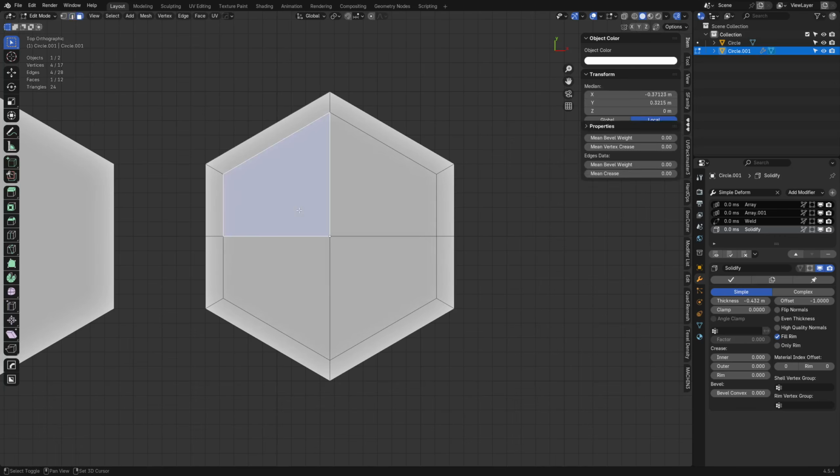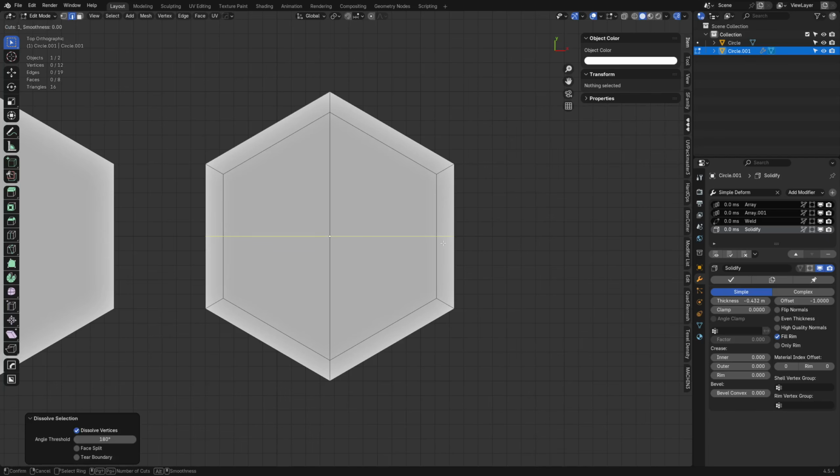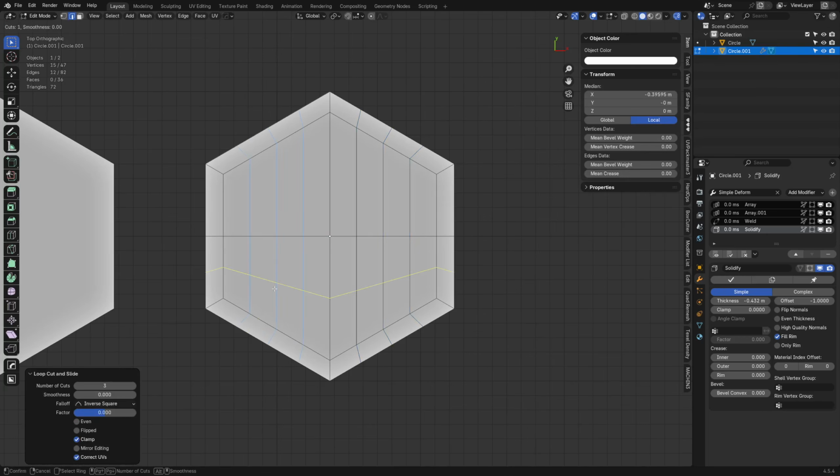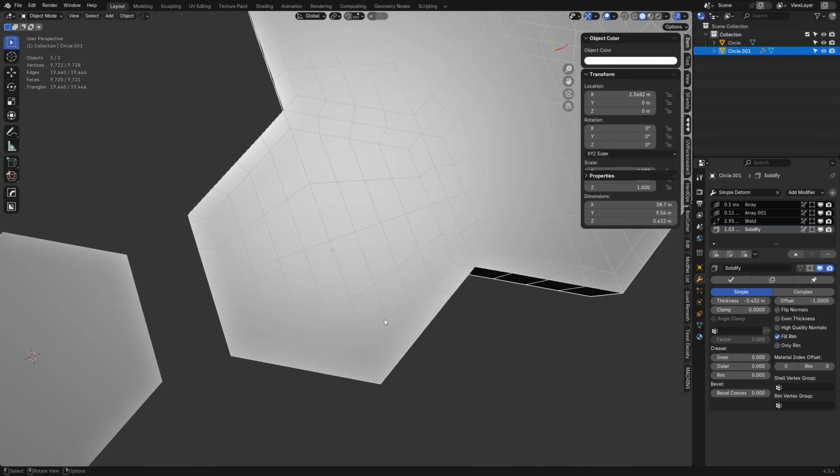Solve those first. Say we had an n-gon in here. We want to do things like this manually. Just remember, two verts, hit J. These might not exist right away, so you would add a loop cut. Boom. Okay. Then you can add loop cuts after. You do your 3 here, your 3 here. You do your 1 here, 1 here. Okay. That's how we get back to that.